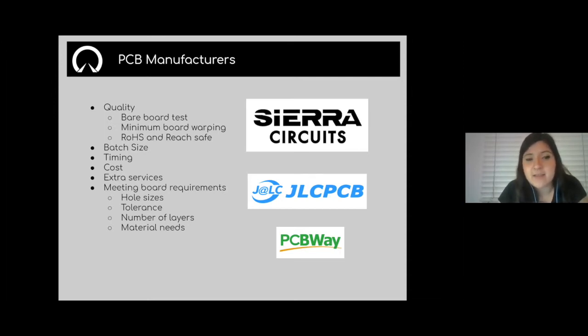And just lastly, will the manufacturer meet your design constraints? Can they drill your hole sizes? Can they meet your tolerances? Will they print the layer number that you have? And just also material type. Will it be RoHS compliant? Do you care if it's a lead or lead-free board?